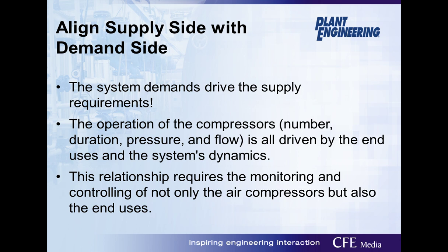The real key of knowing what that is and why you want to do that is to be able to align the supply with the demand, because each one of those different operating patterns or operating modes is going to have a different usage. And so we need to align that supply with whatever that demand is. We really want to understand that the system demands drive the supply requirements: the number of compressors, the duration, all of that, and the system dynamics tell you what's happening in the system. And again, we have to have the right number of compressors to be able to control that.